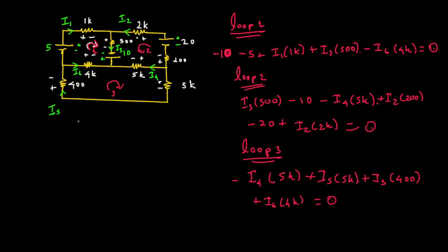Then next thing we can do is analyze the KCL. Kirchhoff's current law can be analyzed at each node. So wherever you see a junction with multiple currents flowing, that's a node. So here this is a node. Let me use some different color over here. So this is a node right here. Okay, and multiple currents. If you look at this one, only I1 is flowing. This is only I2. So these are not nodes. You have to look at the junction.